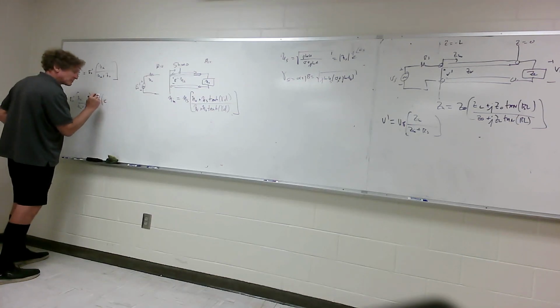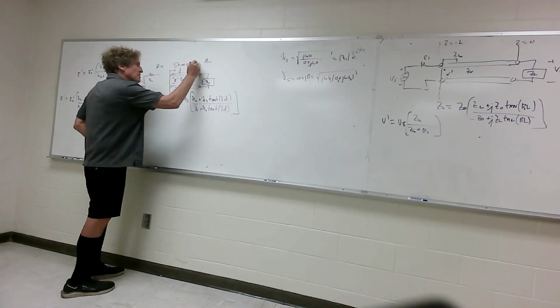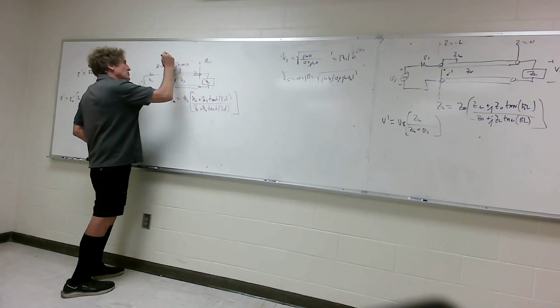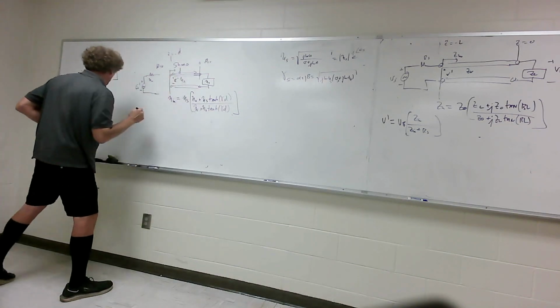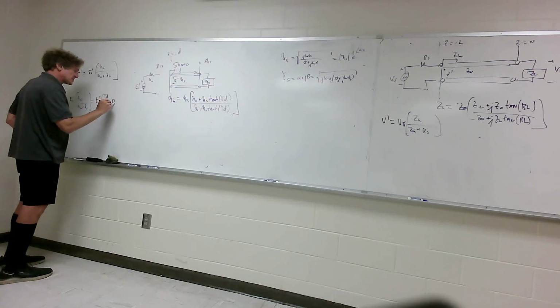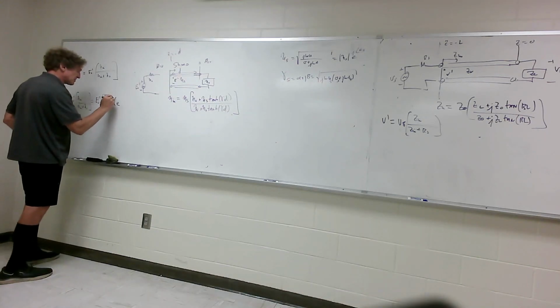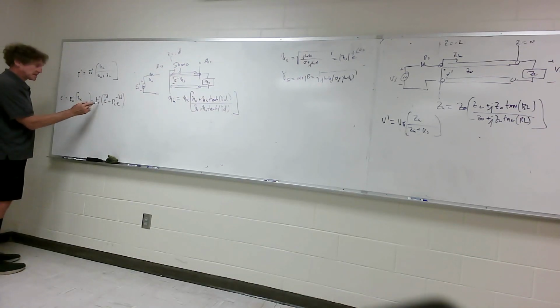Now normally it would be minus gamma times D, but because I'm putting this at 0 here, and this point would be at Z equals minus D, then this is going to be E to the positive gamma D plus the reflection coefficient below times E to the minus gamma D. That's E shield, which is what I need, E0 shield.